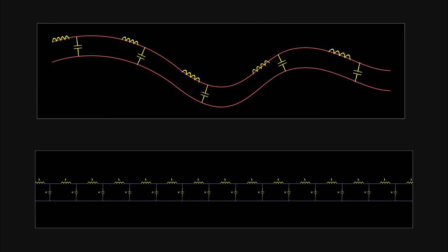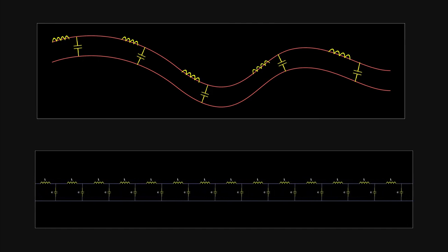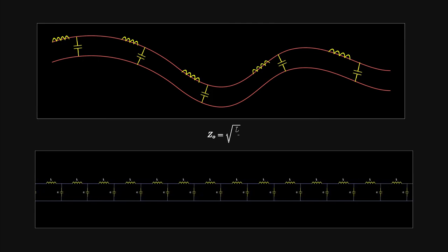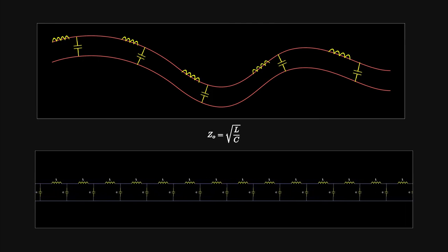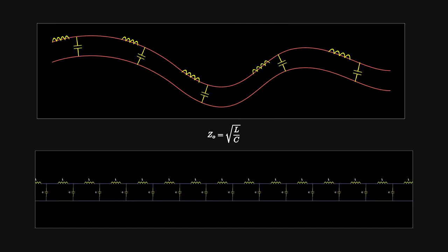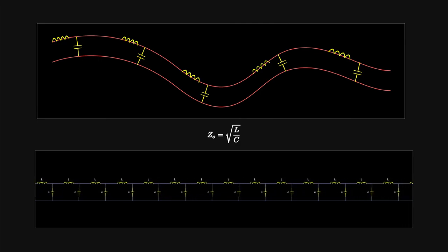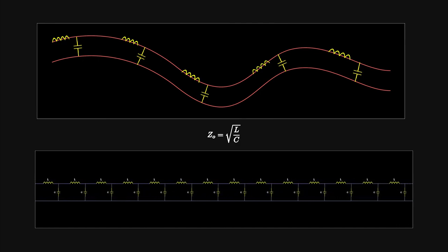And we saw that this infinite number of inductors and capacitors is equivalent to a real impedance called characteristic impedance. This impedance does not absorb power. It only establishes a relationship between the voltage wave and the current flowing in a line. Before reaching the load, while the signal is traveling through the line, it is still blind to any kind of termination on the line. It can only see the characteristic impedance of the line.